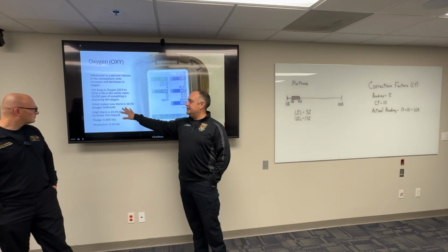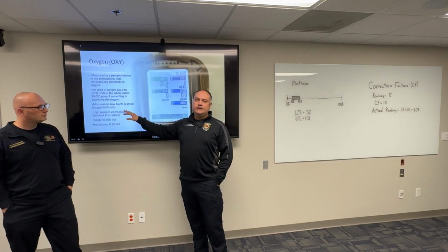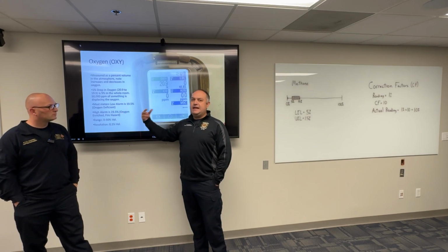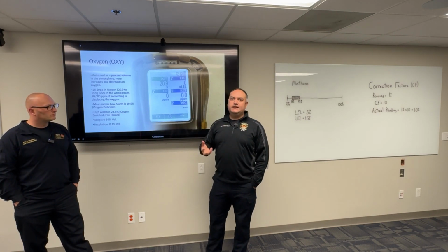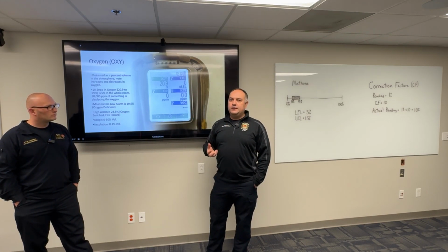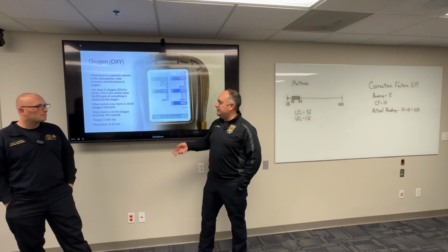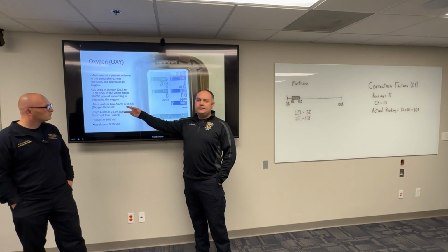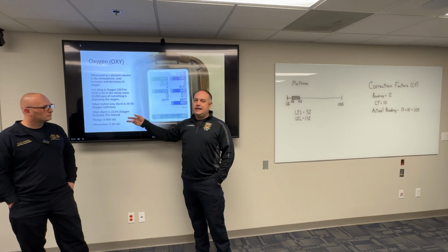Now, the hazards with oxygen deficiency, obviously we need oxygen to breathe and to function as human beings, but with our high alarm, it's a hazard because it could be a fire hazard. Everything's more susceptible to flame up or catch fire if it's oxygen enriched. Those two set points are defined by OSHA, and that's why they're 19.5 and 23.5 on most of your meters.